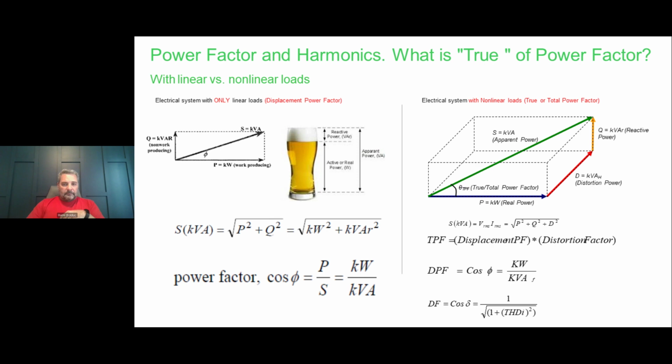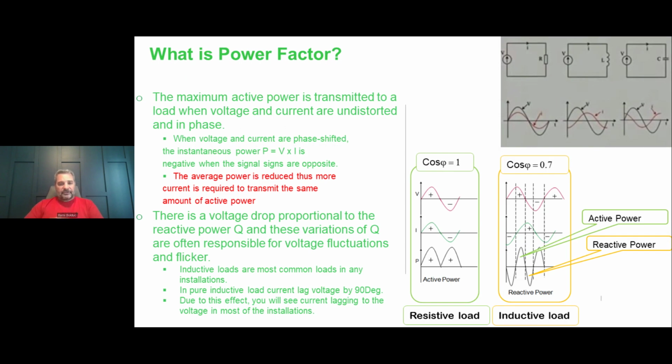Okay. So here we have an example, and we can see how, when you have a power factor of unity, which is when the kilowatts are equal to kVA, you basically have your best transmission capability in your network, where there is no waste, let's say, of current being transmitted. But when you have a poor power factor, you need to transmit additional current to transmit the same power through your network.